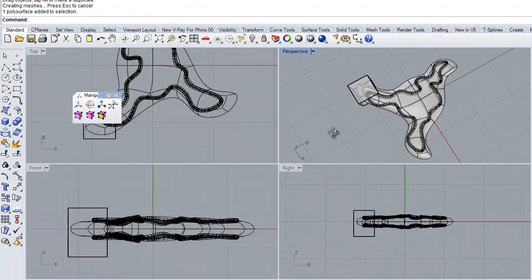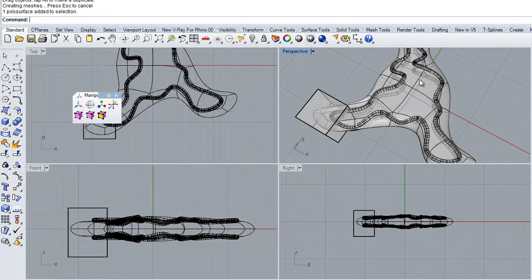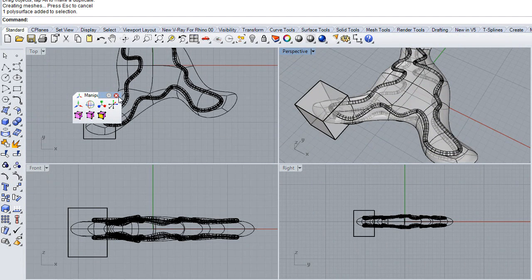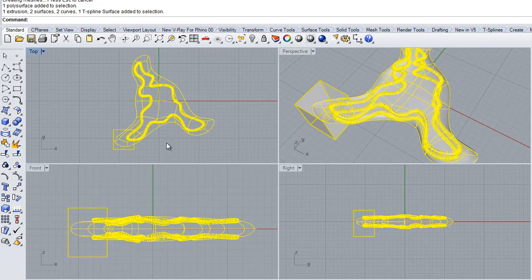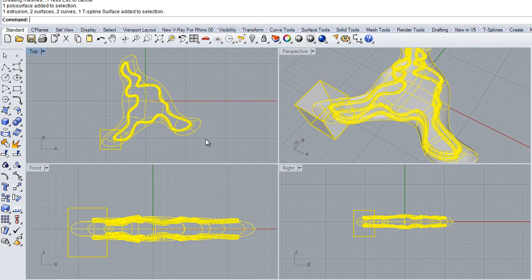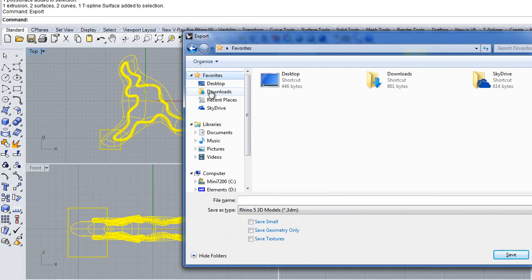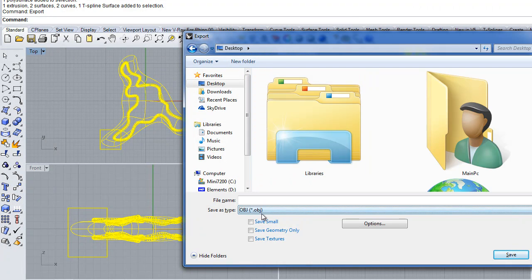All right. So we have this object, and we'd like to apply a stamp to the middle of it that we've got ready in 3D Coat. There's a couple of ways for you to export this now. If you drag all of this and you go export, I don't know if it's going to turn that into a Rhino surface or into a box mode surface or not. So I'm just going to go export, and let's test it while I've got it. Export desktop, OBJ. You can use STL or OBJ. I don't think it really matters one way or the other.